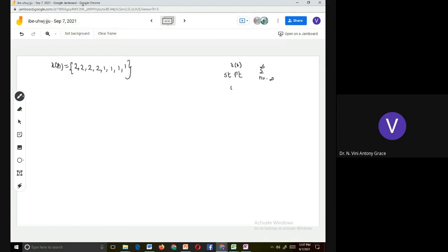of x of n and h of n, because one of the sequences is folded, shifted, multiplied and added together. So it is definitely required to find where y of n starts, because the length is from minus infinity to infinity. But it is not the case in circular convolution. Circular convolution has only a finite number of input samples, and you get the same number of samples at the output. Okay. Will you start doing this problem now?